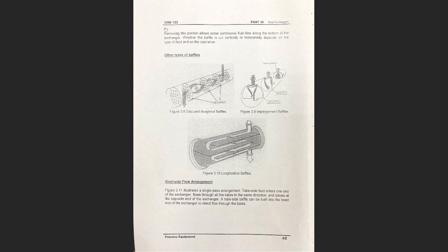You see when the fluid is flowing from the top like so, usually it flows at a very high speed, guys, and you would like to slow it down a little bit and distribute the liquid instead of flowing into a single point inside the heat exchanger. So they place a baffle like this so that the liquid, once it flows into the exchanger, hits that plate, causing its velocity to slow down a little bit. As a result, the liquid gets distributed properly inside the heat exchanger.